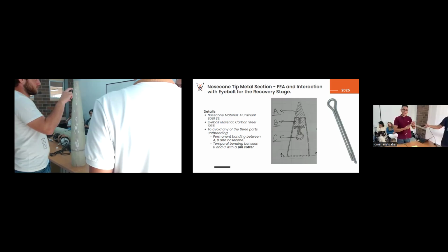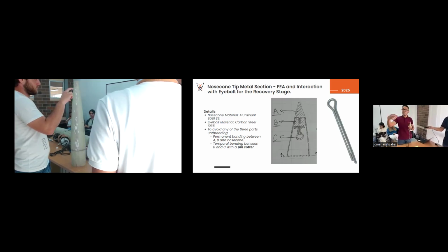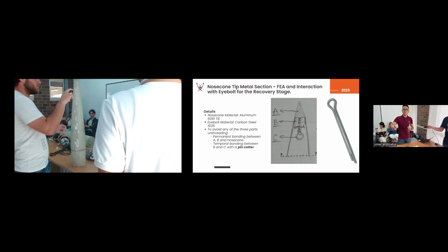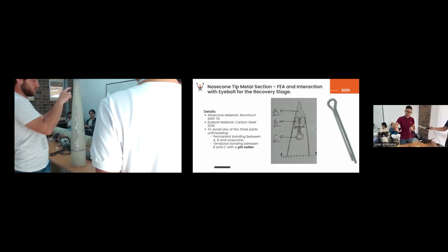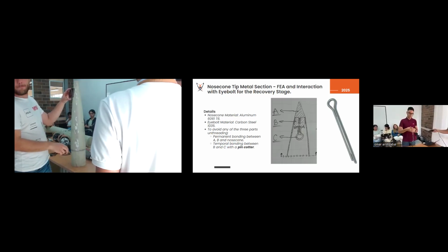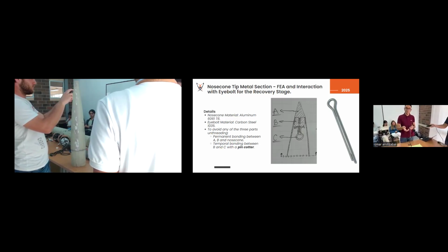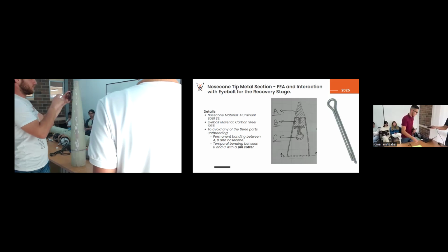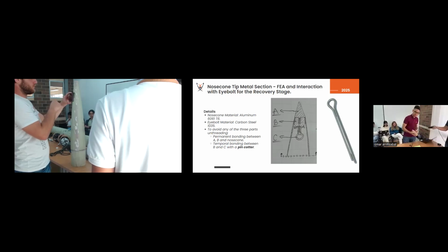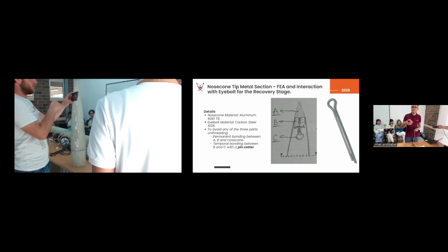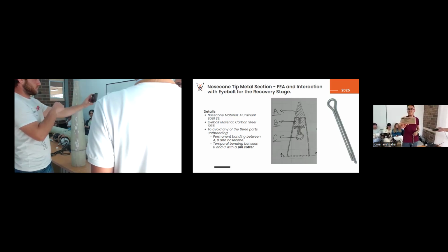And in the tip section, we are going to assemble it to the fiberglass nose cone, the body nose cone, and realize a permanent bonding with a special epoxy adhesive, that you see here.